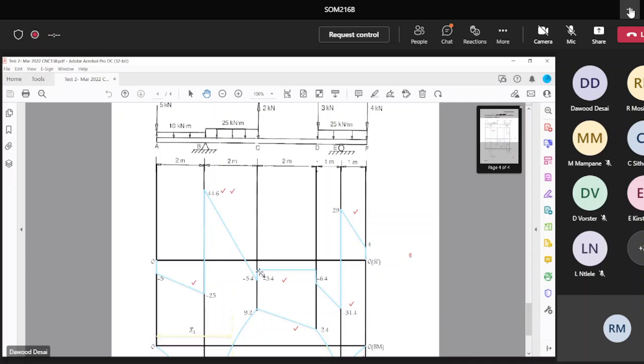But in exams, you do not put kilonewton meter, you put kilonewton per meter, which a lot of students make a mistake on. They will put -1 there. The moderator is very strict, so I mark very leniently on the test. Right, so the bending moment at D works out to 2.4 and the bending moment at E works out to be -4.